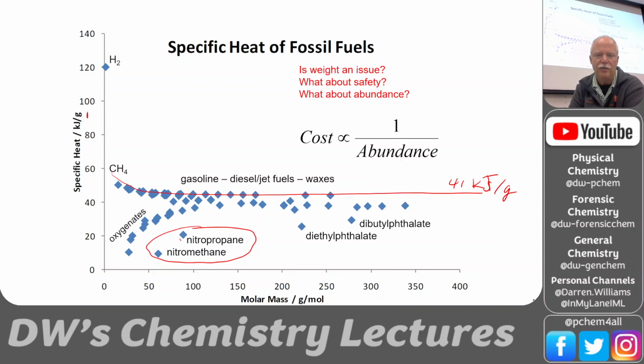It's not really the nitro that is giving you the extra energy, it's the oxygen it's providing. So when it decomposes, then it's a less energetic penalty for producing the oxygen, so you can stuff more oxygen into the cylinder. And it's also nitrous oxide, not nitro, not nitrated organics.